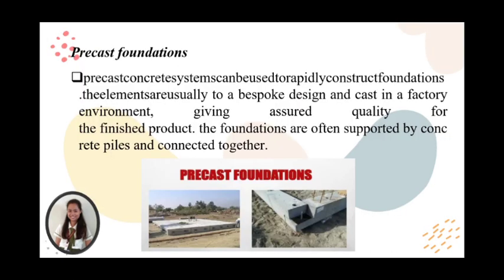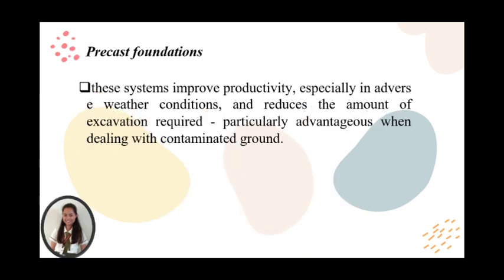The last method is the precast foundations. It is an off-site construction technique in which the foundation units are pre-engineered and manufactured in a controlled environment. These units are pre-engineered, so their capacities or limits are communicated with the purchaser to produce the desired unit.